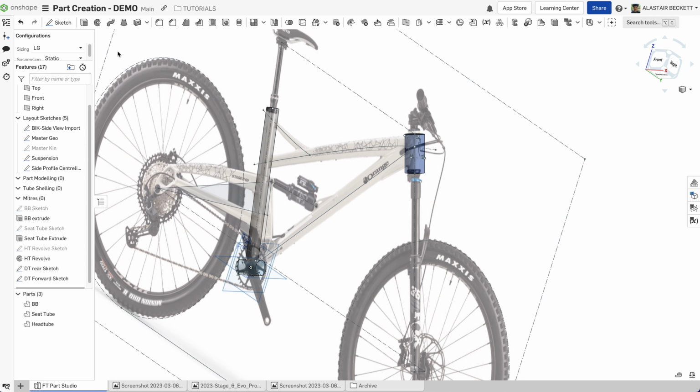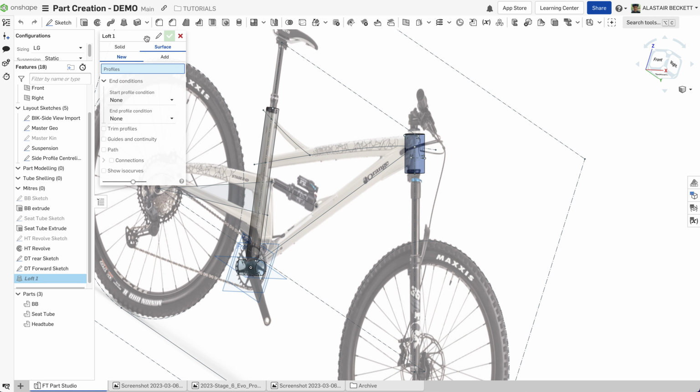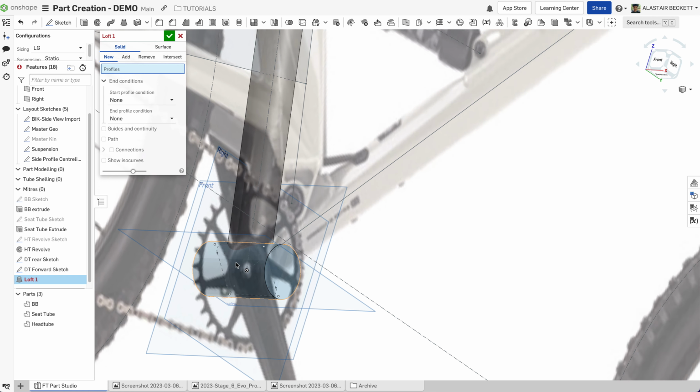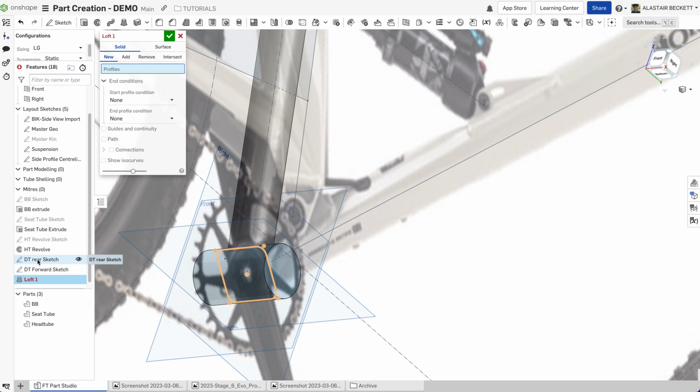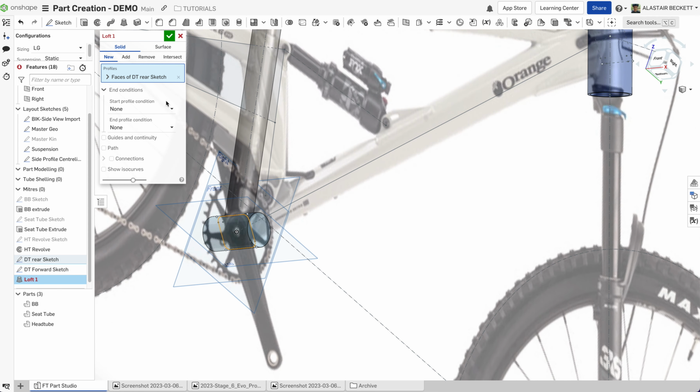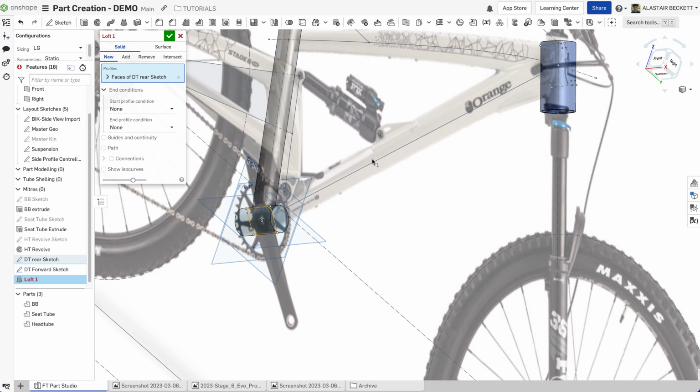Okay, so this is how the Loft tool works. You select it here, Loft. Again, we want to make sure we're on solid and not surface. And if you can find the part here or your sketch, you can click on it, but if not, you can just click on this one here. Some of the tools in here require you to select a different box before you pick the end one, but with Loft you don't, because you can select multiple. You could have another midpoint sketch here if you wanted and click that, and the Loft command would figure that all out as it goes.